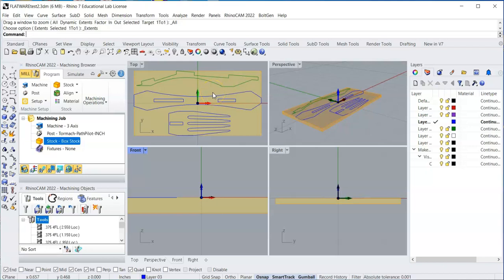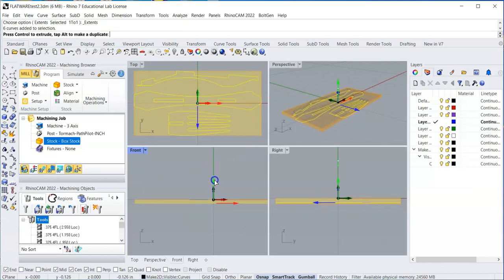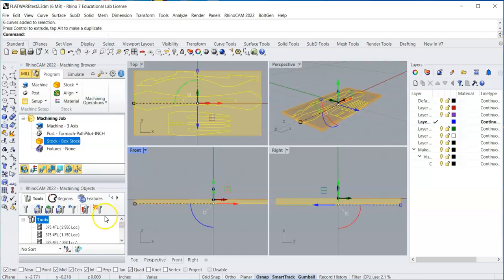What would happen if you did not align it to the top of the stock? Well, let's just do that, I'll show you. If you had it right here, down in the bottom, and you told it to mill an 1/8 of an inch deep, it's going to mill an 1/8 of an inch immediately from the top of the stock down. So you'll be milling into the table immediately and milling through an 1/8 inch instantly, even though you wrote the program for multiple steps below. Does that make sense? So that's what would happen.